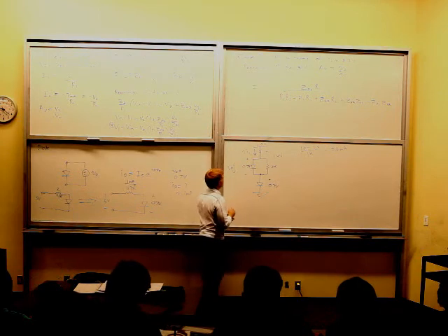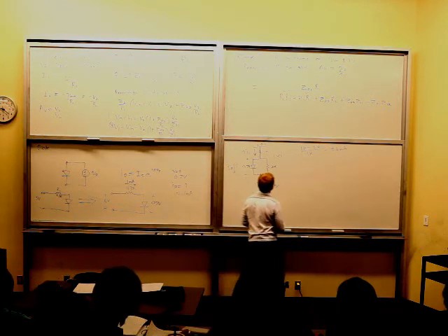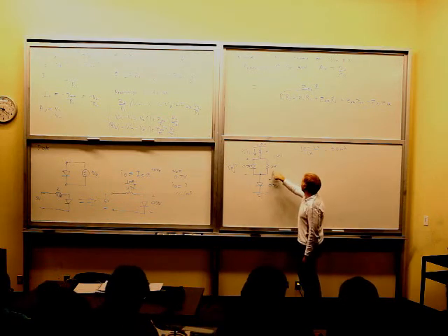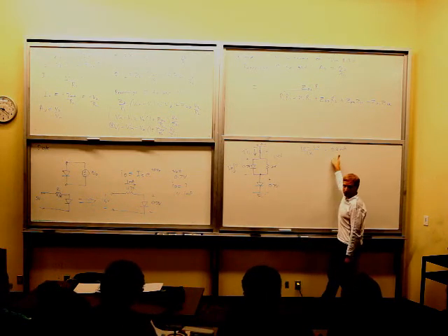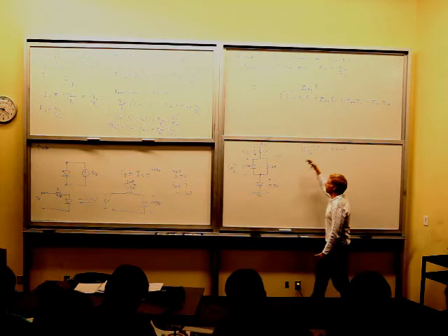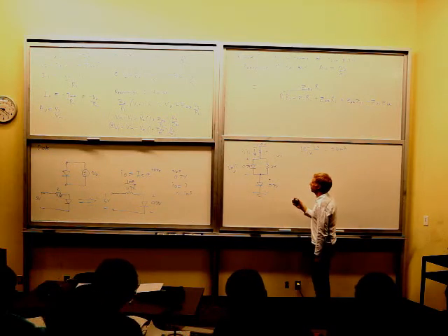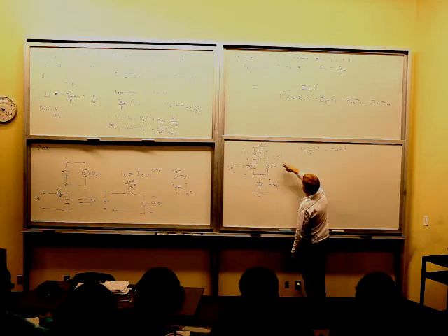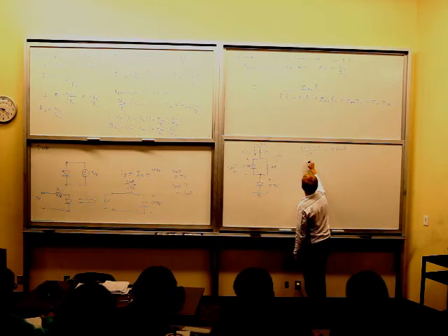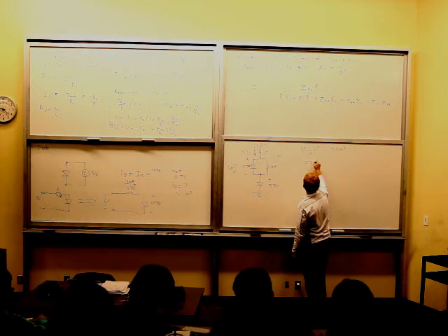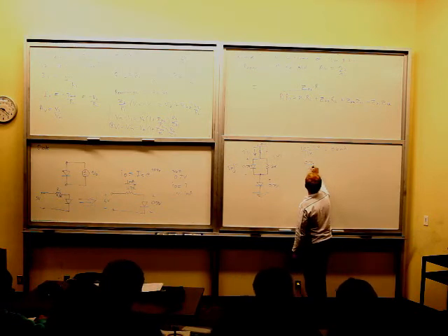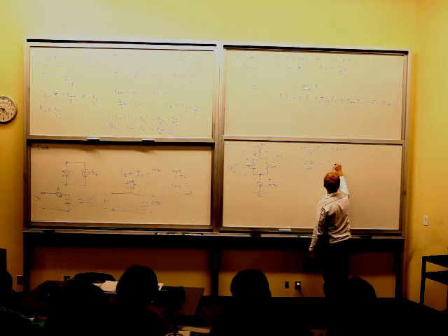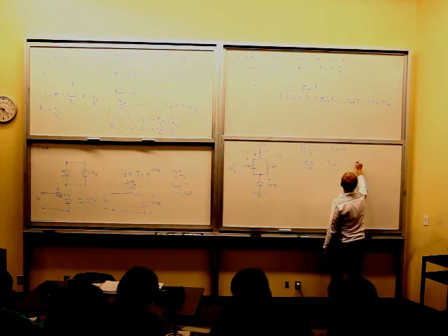What's the current through that diode? Well, I know that the current through this diode plus the current through here must equal 8.6 milliamps, right? The current has to go through those two branches. So the easy target here is the 2K. So there's a 0.7 volt drop across this 2K resistor. So I'd say 0.7 volts divided by 2K plus that other current, ID1, must equal 8.6 milliamps.